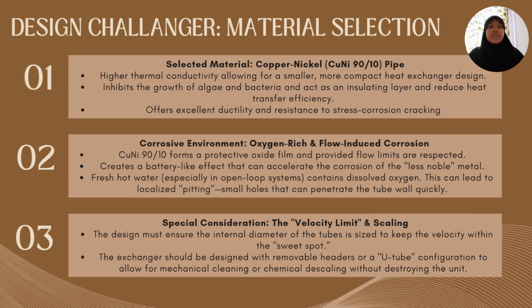Material selection was the major challenge due to the corrosive nature of the fluid. We selected the copper nickel Cu90/10 for the tube. Why? It offers high thermal conductivity for a compact design and naturally inhibits the growth of algae and bacteria. For corrosion resistance, it forms a protective oxide film, which is vital in the oxygen-rich environment that might otherwise cause pitting. We also recommend a U-tube configuration to allow for easier mechanical cleaning and descaling.